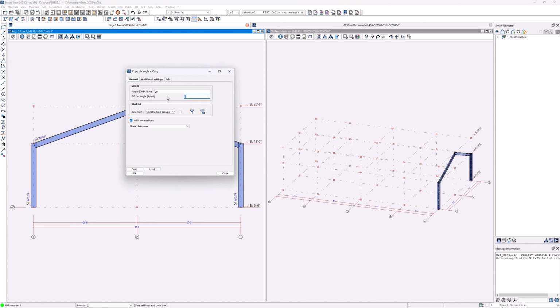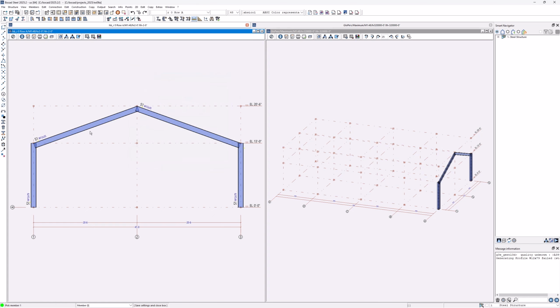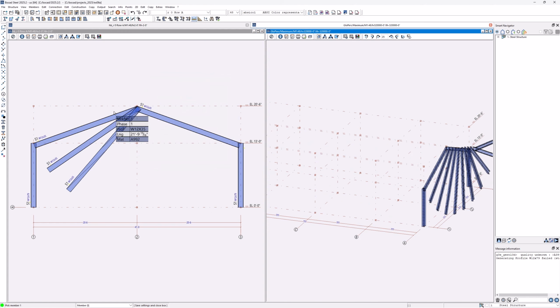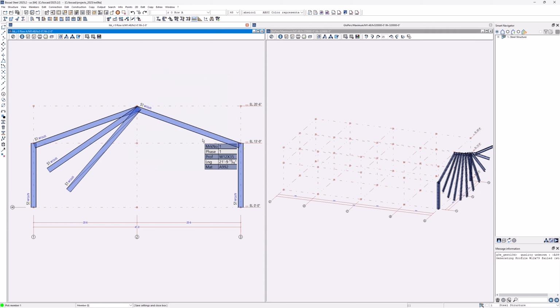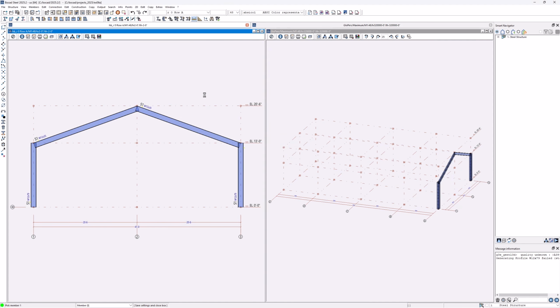If you were to add an offset for each copy, you could go as crazy as saying 10 times 15 degree. Every copy has an offset of 12 inches. OK. It's not too representative right now, but pick the element, pick a point, and each and every copy will have an offset. This would allow you to cover certain situations of, for example, a spiral staircase. We're not in that right now, but you get the picture.